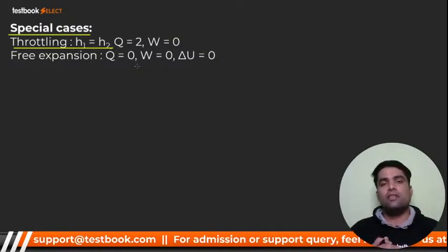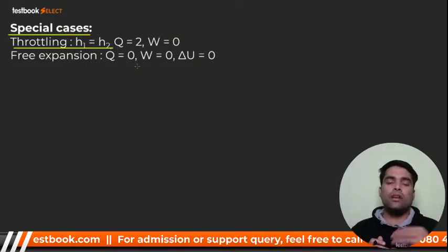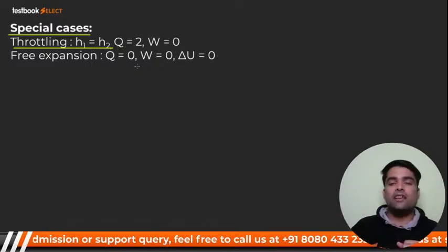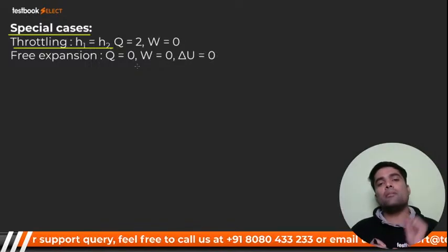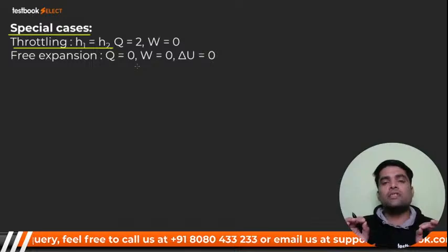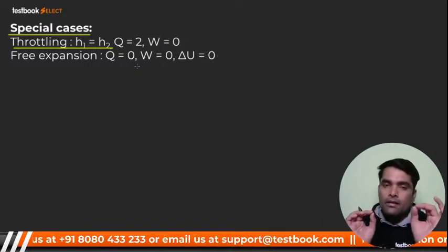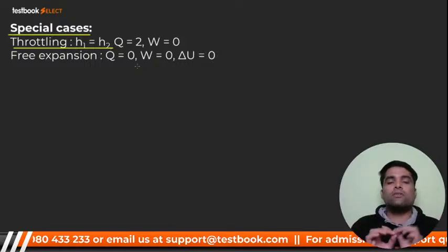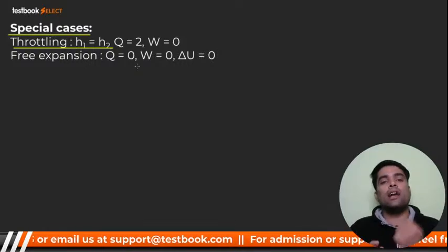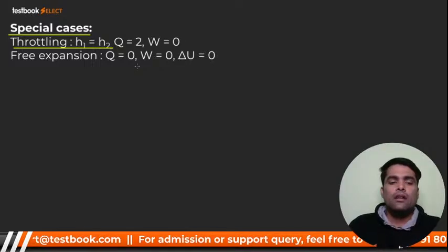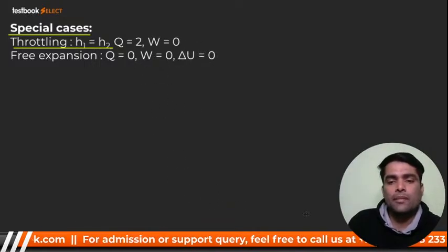There are three cases. Sometimes pressure drops, sometimes temperature drops along with the pressure, sometimes temperature increases, and my dear, sometimes temperature remains constant. So temperature remain constant किसमें होगा? आइडियल गैसेस के लिए. When we are talking about real gases, उसमें temperature increase होगा और decrease होगा, and it is highly described, बहुत अच्छे से describe किया हुआ है Joule-Thomson coefficient, right, and it is highly irreversible, keep in mind this thing.